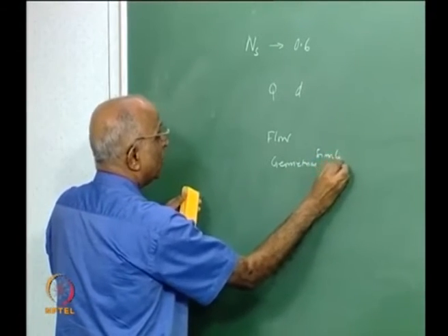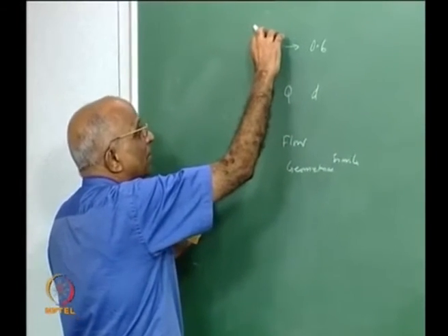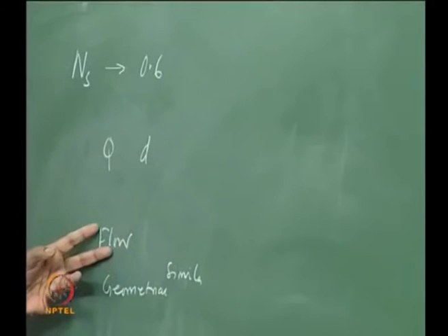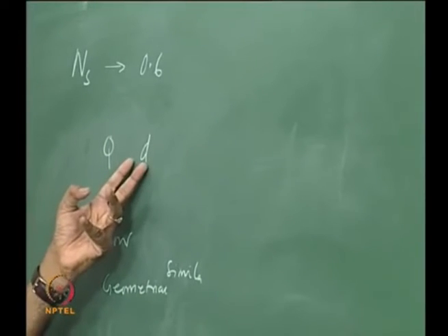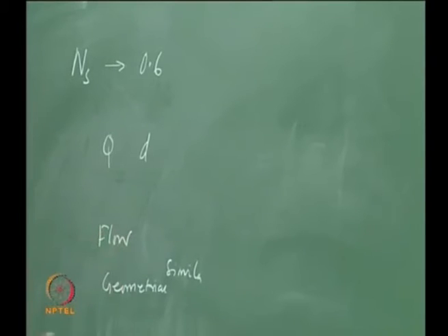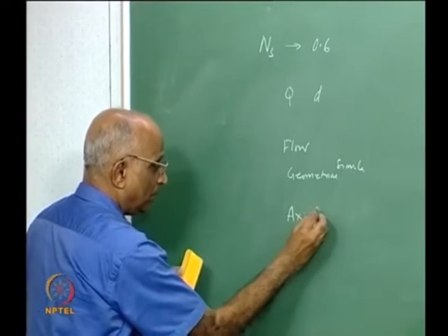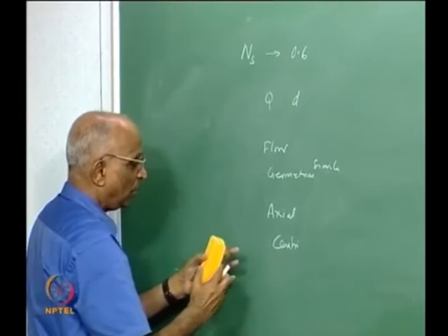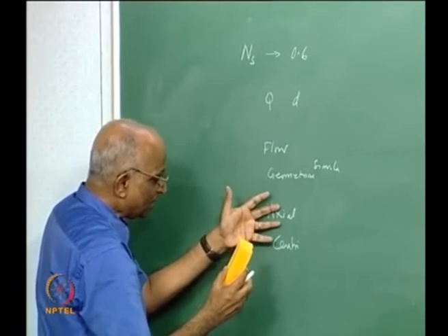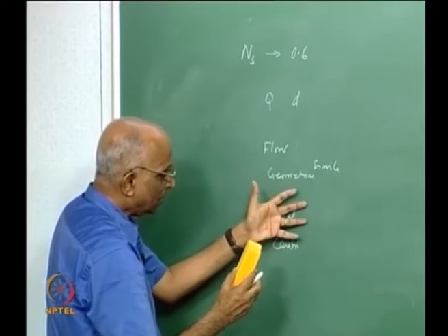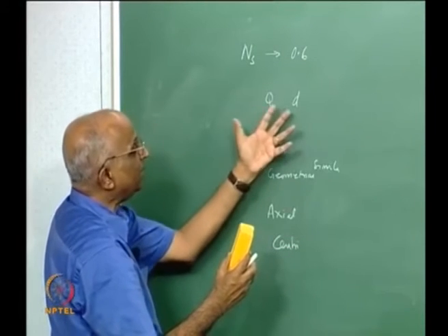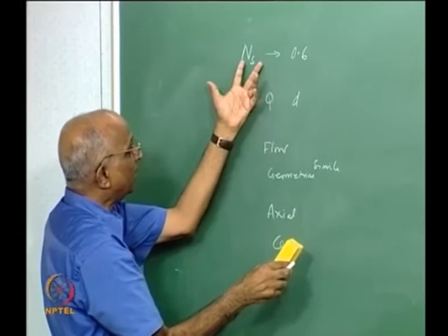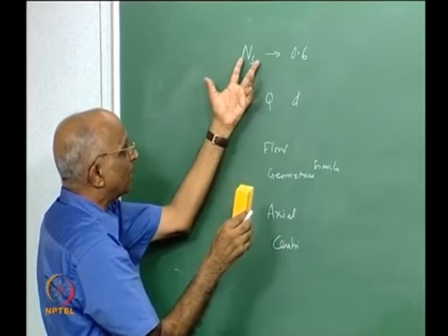In other words, for the same non-dimensional number, that is the same specific speed, I can assume for different values of Q and different values of diameter, for a given type, it could be axial, it could be handling a particular type of propellant, or it could be centrifugal, or a combination of some of these things. For a given axial flow machine handling a particular set of propellants, if I keep on varying the quantities and the size, the number is invariant.